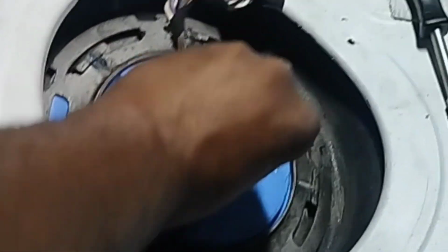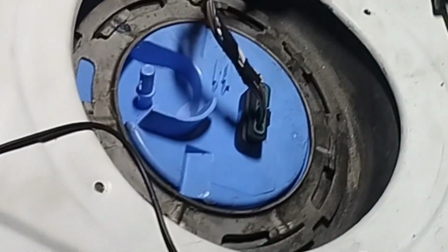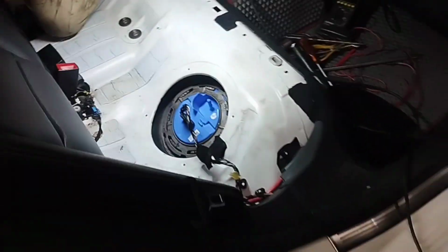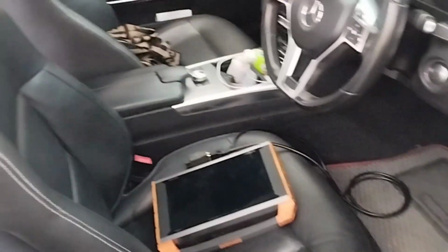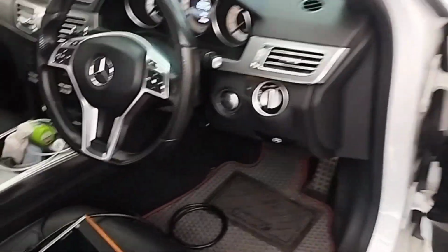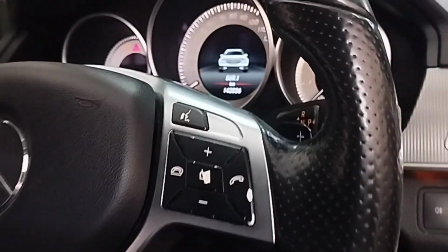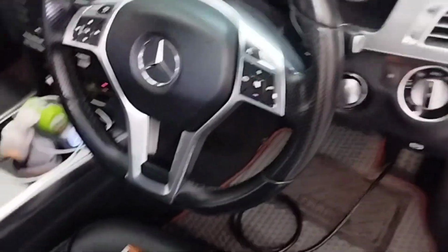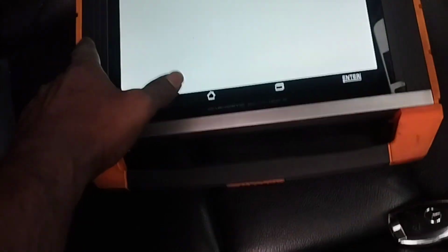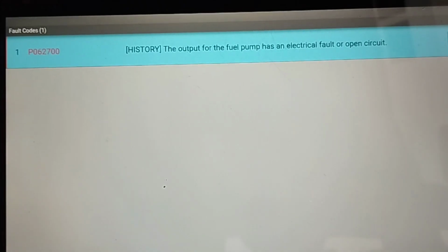We'll connect the socket of the cable with the fuel pump. Complete by installing the fuel pump. The engine code must first be cleared with a scan computer. Turn the ignition key switch to the on position to clear engine codes. The fault code is displayed once more before the engine code is cleared.